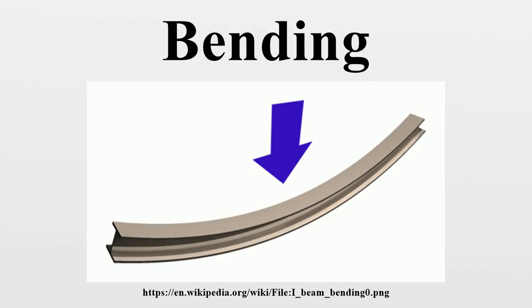Because of this area with no stress and the adjacent areas with low stress, using uniform cross-section beams in bending is not a particularly efficient means of supporting a load, as it does not use the full capacity of the beam until it is on the brink of collapse. Wide flange beams and truss girders effectively address this inefficiency as they minimize the amount of material in this understressed region.